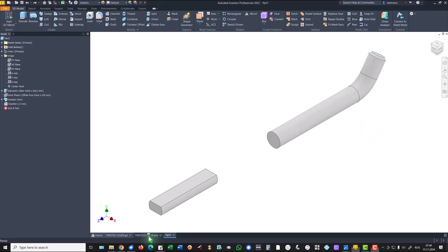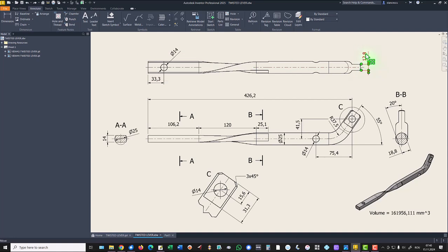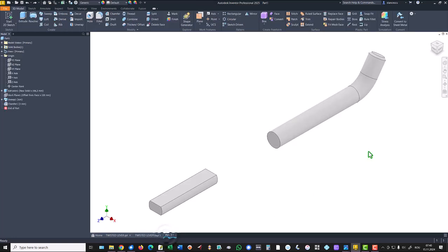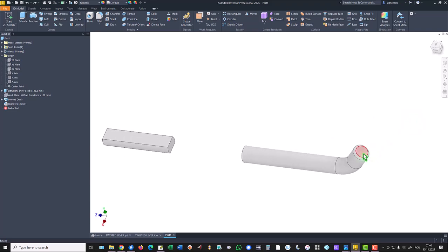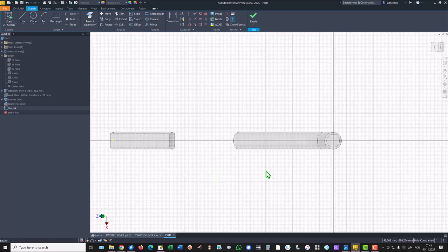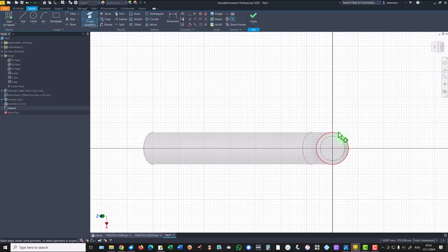This end has a cut at 12.8 on a length of 31.3. Let's apply this cut. We use this circle. We project this. We draw a line horizontal, which is vertical because of the position, and another one here. Now you know that applying equal to the two, we have a symmetry. Dimension is 12.8.